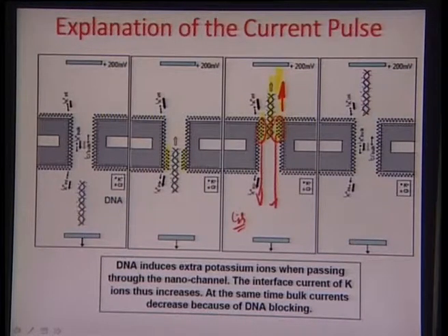So this essentially is an opposite effect than the micro scale Coulter counter, in which you have no such effect, because you are talking about a micron scale object. Whatever the flow is across that micron scale gap is a bulk flow, but here, because we talk about more in terms of almost a single ion level of what is going on, this counter ion effect becomes very important, okay. So you can think of that this counter ion cloud which is going with the DNA into the pore, when the DNA escapes, it is released back into the solution in the reverse side, as a result of which there is an increase or a peaking effect rather than a dip down as is normally observed in other cases, okay.